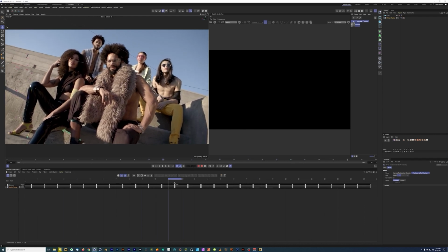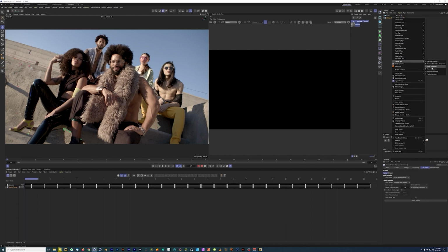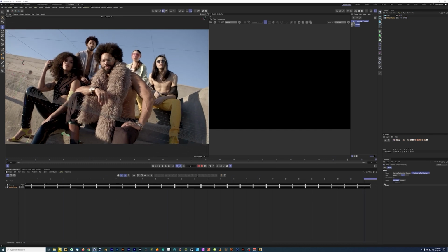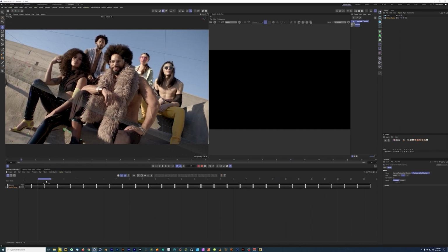Okay, now do we have anything that we know for a fact is a Y axis to calibrate from? Well, these two, it's not perfect, but it doesn't have to be for this shot. So I'm going to make another tag. I'm going to make a vector constraint again, and I'm going to put it between this point right here and this point right here, and I'm going to tell it that that's the Y. So now let's see what we got. Ooh, that messed it up. Now it messed it up.